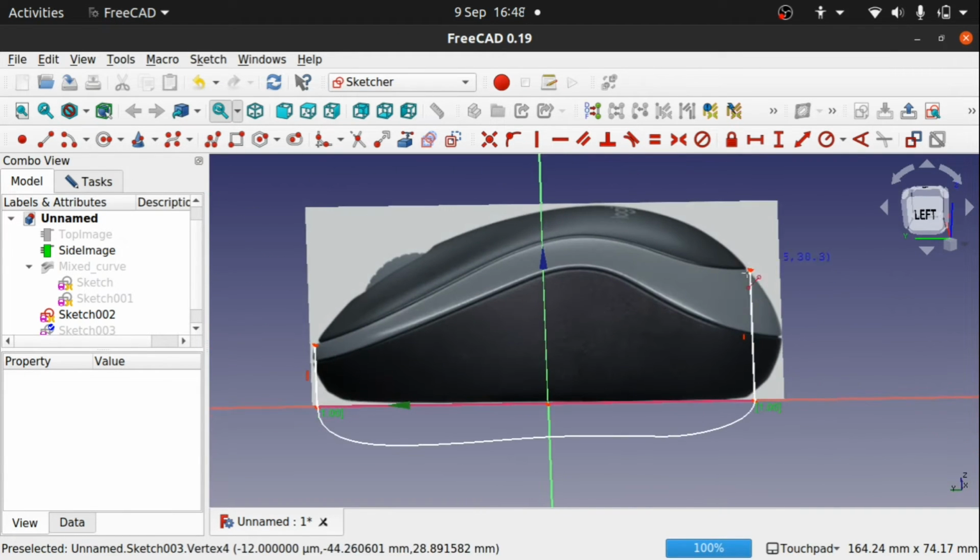So those are in place. We can now use our B-spline tool and start sketching. Remember, starting beyond, coming in, connecting to that point with the auto constraint, and then following the line, and connecting back up and clicking beyond. Hitting escape.